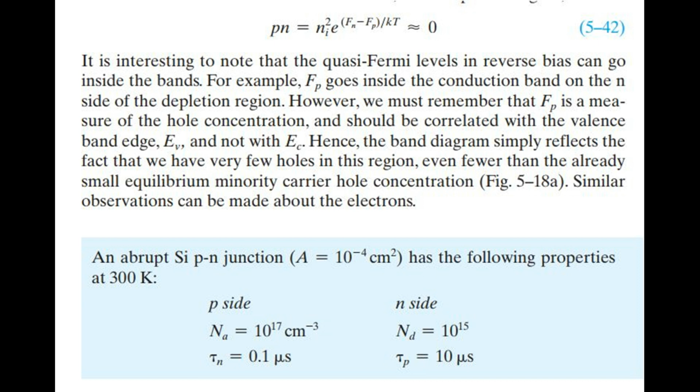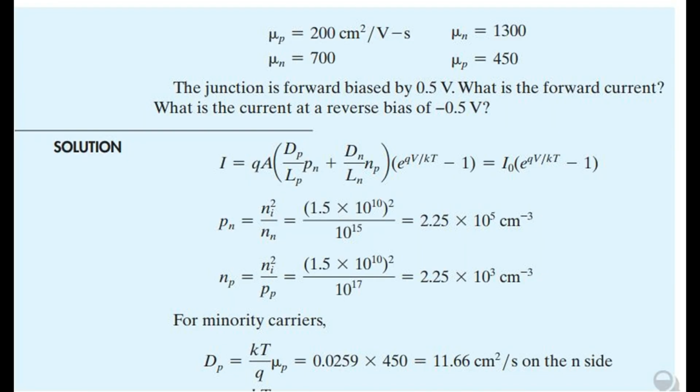We have found that a p-n junction biased in the reverse direction exhibits a small, essentially voltage-independent saturation current. This is true until a critical reverse bias is reached, for which reverse breakdown occurs, Fig 5-19. At this critical voltage, VBR, the reverse current through the diode increases sharply, and relatively large currents can flow with little further increase in voltage. The existence of a critical breakdown voltage introduces almost a right angle appearance to the reverse characteristic of most diodes.